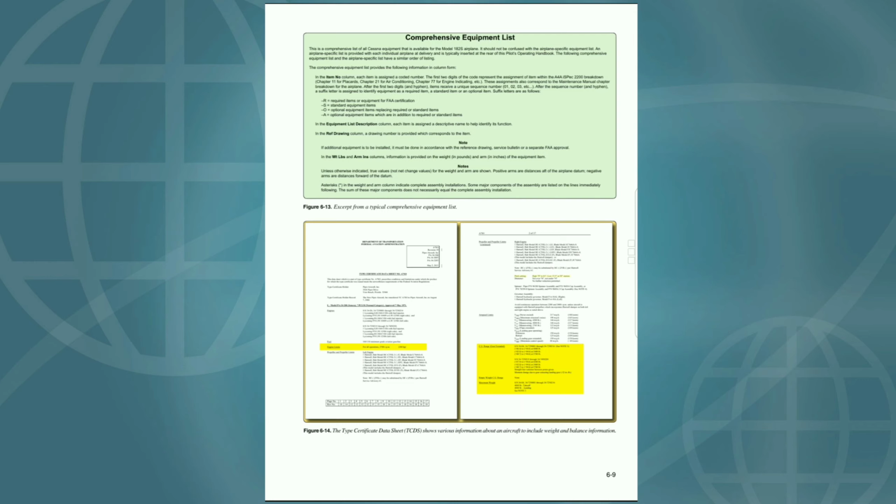Pitch setting: high 79 degrees to 81 degrees, low 13.5 degrees at 30-inch station. Diameter: not over 76, not under 74. No further reduction permitted. Spinner: Piper P/N96388 spinner assembly and P/N96836 cap assembly, or P/N78359-0 spinner assembly and P/N96836-2 cap assembly. See Note 4.